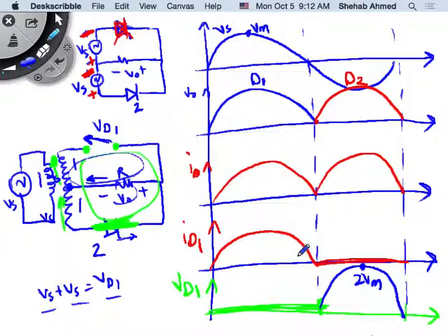I mean, if you would go on the vendor's website, for example, and compare buying 4 diodes that are 30 volts versus buying 2 diodes that are 60 volts, I'm pretty sure that buying 2 diodes that are 60 volts will be cheaper than buying 4 diodes that are 40 volts. The limitation is, of course, here you need a transformer as well. Actually, in most cases, when you connect to the utility, you will have to have a transformer. So that may be something that you will have to have anyway in both circuits, right? So if you do the numbers, this is not a bad circuit to have. It's a nice circuit to use.